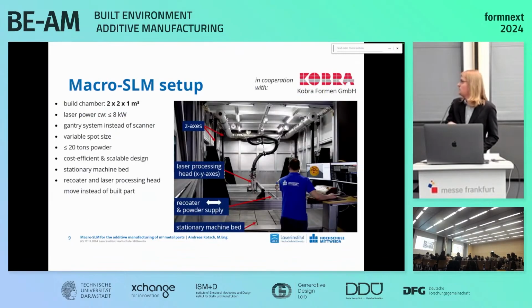Yeah, it would have been in the video. Unfortunately, it did not show. But below the laser processing head, there's like a hood of argon flow. So it's a local argon atmosphere. It's not a perfect environment. We are measuring about, let's say, 0.1% of oxygen still, but it's good enough that you only get light oxidation. But it's a big issue, the argon.